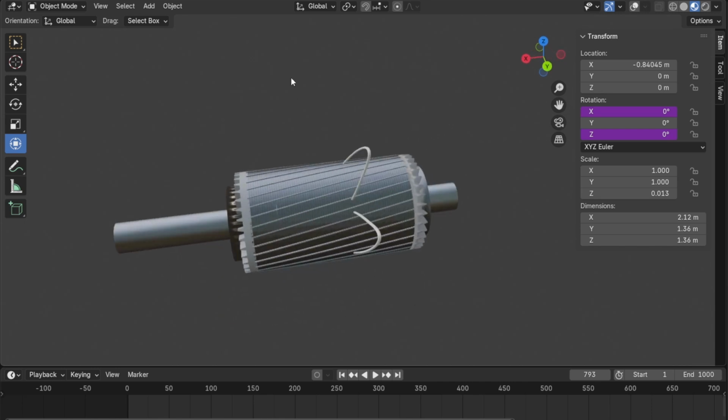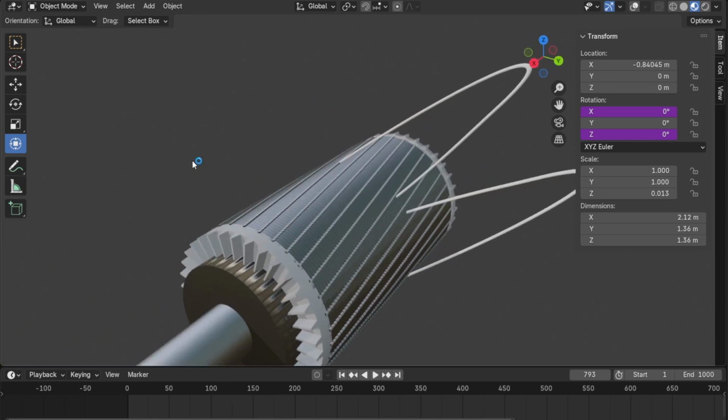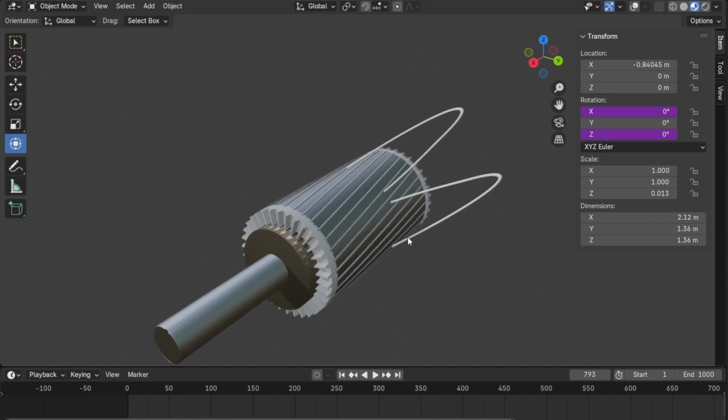And so when the motor starts, your slip is really, really high. And then as the motor warms up and gets sped up, the slip decreases. And then eventually you'll hit a steady state. But that's where inrush current really comes from with these motors. And yeah, let's talk about why bad connections cause the motor to draw heavier current, because that's really a mind bender when we start thinking about that.